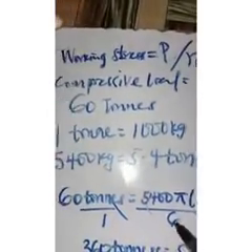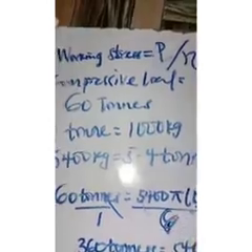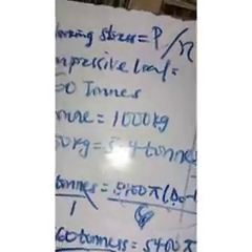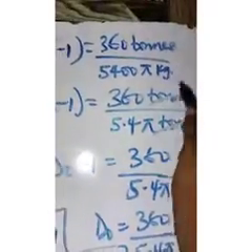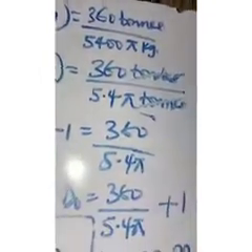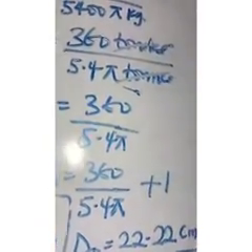You just got this the previous time, and put the safety factor we are given, and it's 6, and I cross multiply 3600 by 5400 pi. From there I divide both sides by 5400 pi. So to convert it to tons, I have this kg in tons, then cancel and make D naught the subject of the formula, and I have the final answer as 22.2 centimeter.